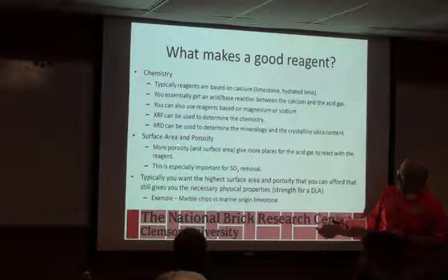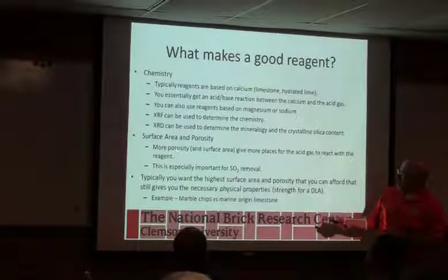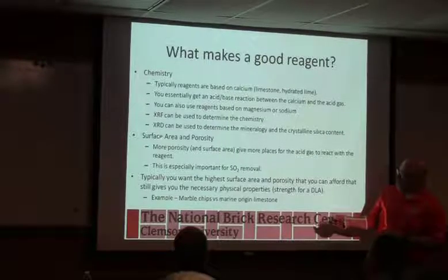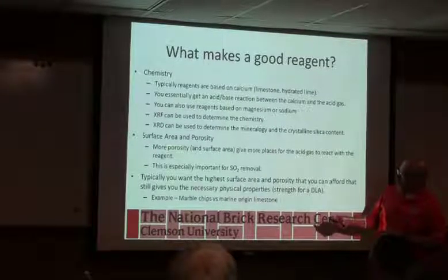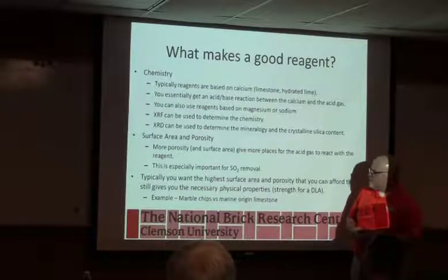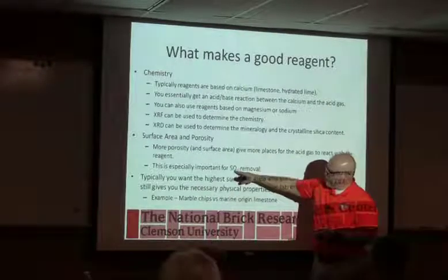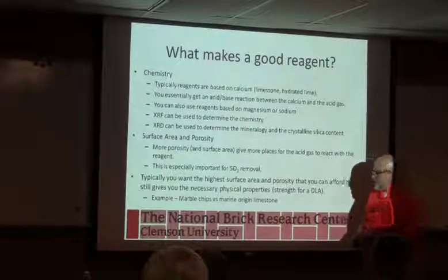We're not so much worried about this for a DLA. Usually they'll work okay, as long as there's some porosity. But for a dry lime absorber, or for a dry lime scrubber, we want to get that porosity and surface area up as much as we can, because it really improves that SO2 efficiency.